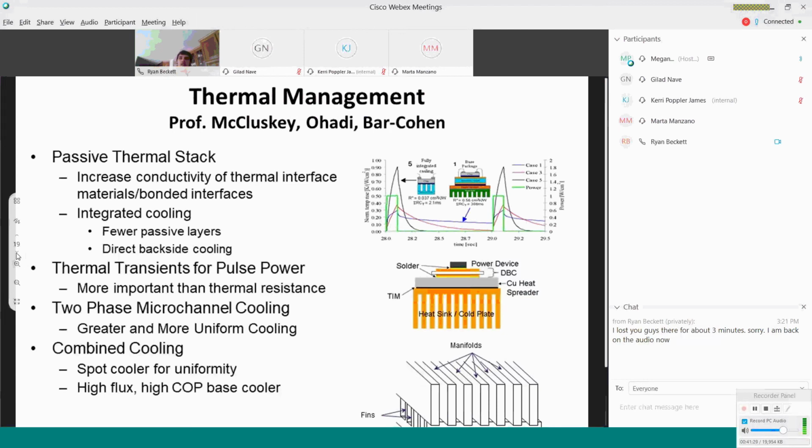And then, of course, one of the most efficient ways to get rid of heat is to use the fact that as you melt something or boil something, it absorbs a lot of heat to that process. So changing from solid to liquid is called a phase change material, and we'll do that to store heat that we may want later on down the line. So if there's a very, very rapid spike in temperature, we may pull that heat out, causing a solid to liquefy, and then later on, when the chip is off, we may allow that heat to slowly dissipate away, re-solidifying the material. That's phase change.